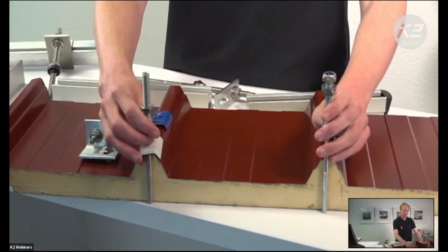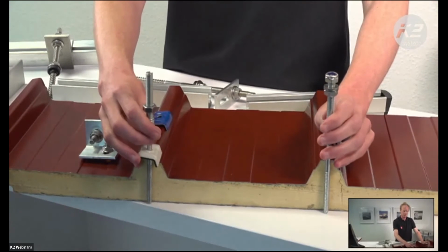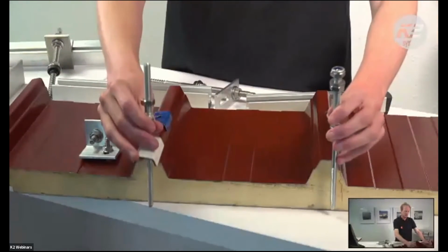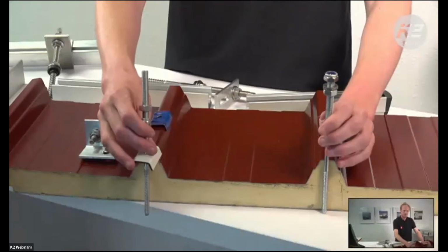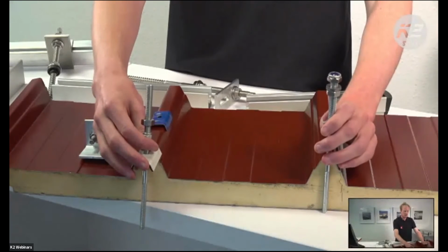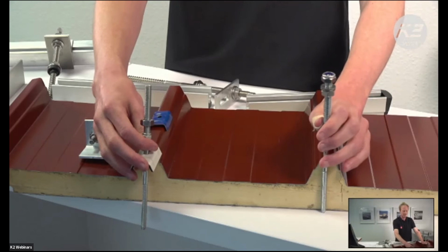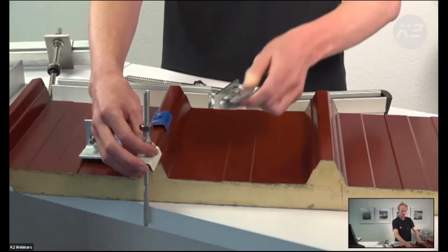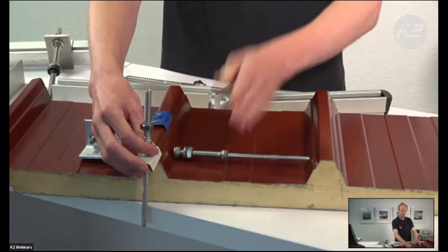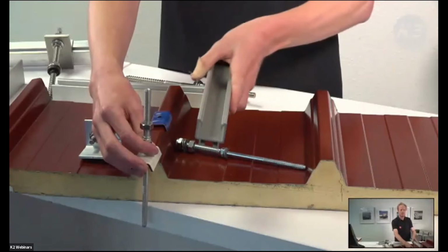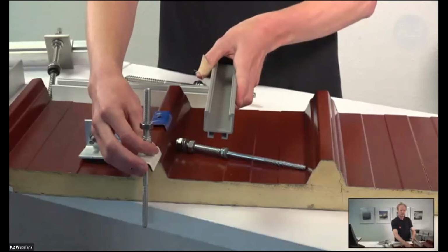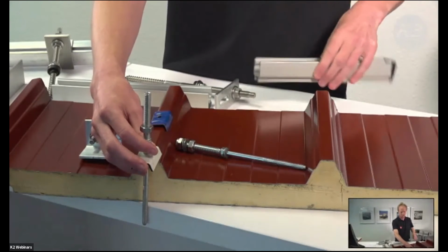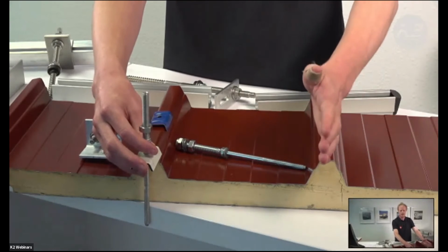So generally speaking, it would be like this. However, both are possible. Your subconstruction would run this way. You can put them on opposite crests. And so in this case, the bridge would sit between the two solar fasteners, and then the rail, so imagine this is the bridge here, the rail runs towards me. So we can halve the loads on the solar fasteners by adding this bridging component, and then we can put a thicker rail in.